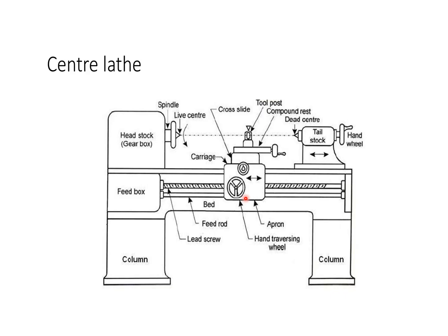Next, feed mechanism. So the movement of the tool relative to workpiece is feed. The lathe tool can be given three types of feed, namely longitudinal, cross and angular. When the tool moves parallel to the axis of lathe, the movement is called longitudinal feed. This is achieved by moving the carriage.